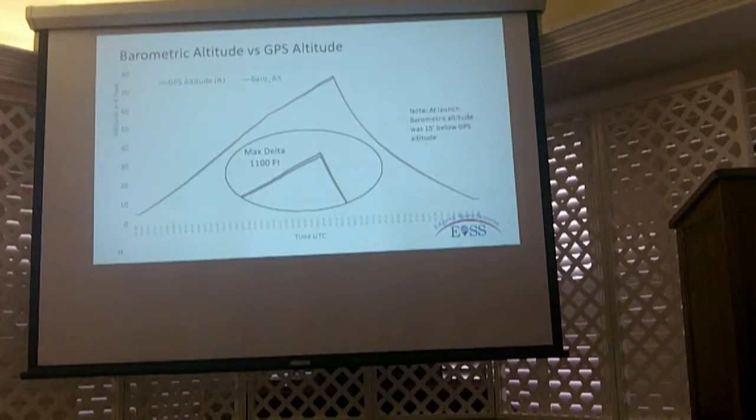For other systems, like for pilots, what is that delta expected to be? Is there any information on the net about what the averages are? What is the average delta between GPS and barometric altitude? Mark, at 18,000 feet, you adjust your altimeter back to 29.92, so that you're not worried about what the pressure is on the ground. Every plane up there is set at the same spot. So we neutralize above 18,000. Yeah, you're separated by pressure altitude, not by absolute altitude.